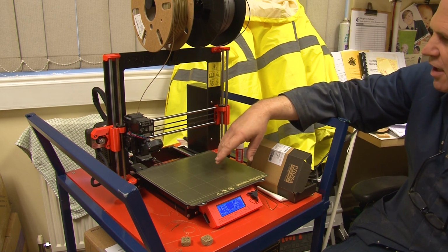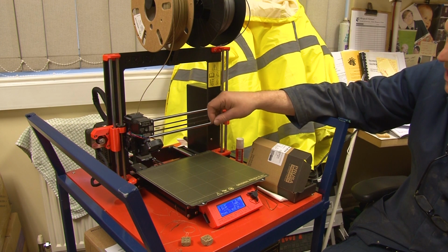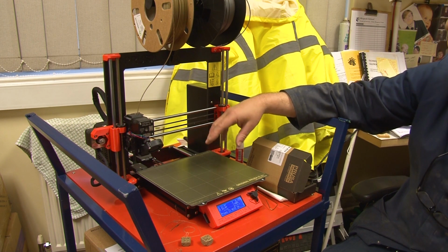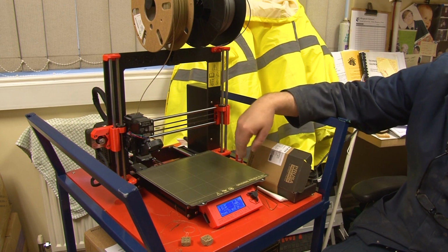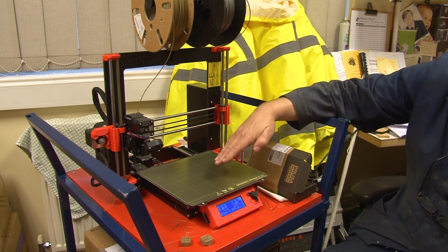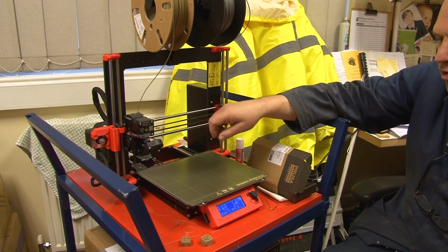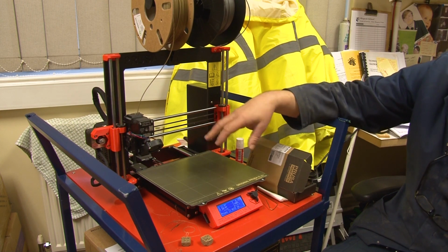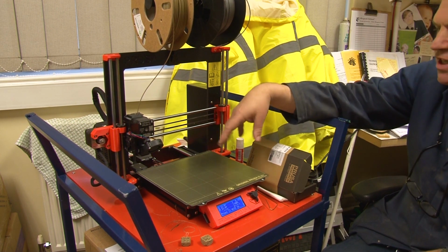We'll see what happens. So the next thing to say before we start the print is I have used acetone, or you can use isopropyl alcohol, but that bed needs to be spotlessly clean each time you print. Any impurities on the bed is going to mean that the item can be knocked off of it easily, or if you were printing something a bit on the thin side, the layers might start to peel off. There's all sorts of things that can happen.